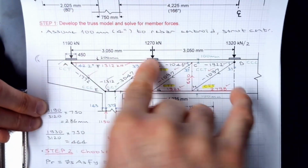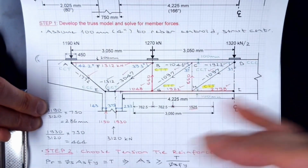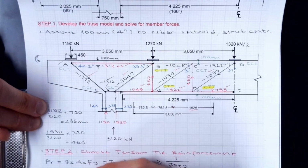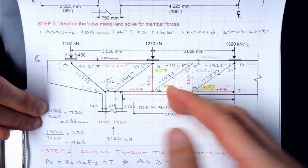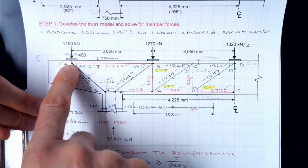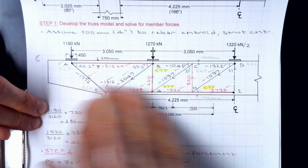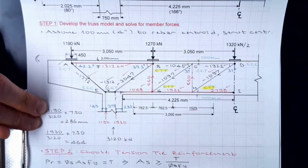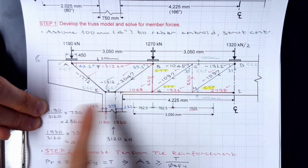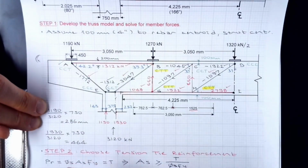So using your procedures, however you distribute the dead load, consultants put half to the top, maybe they allocate the other half to the columns. If you are allocating some dead load to the columns directly, then it's not going to stress your struts. So putting all the dead load to the top would definitely be the most conservative solution, because you are using struts to transfer the entire dead load.